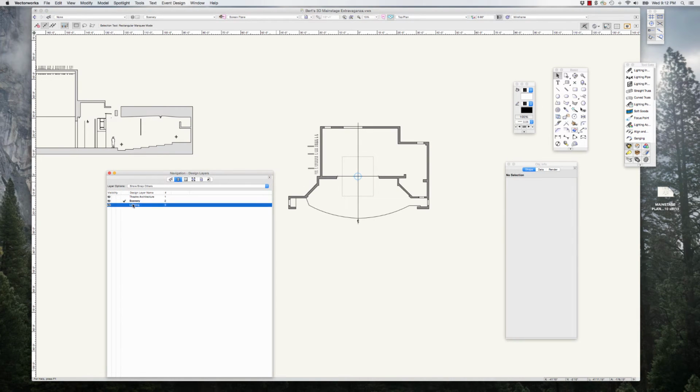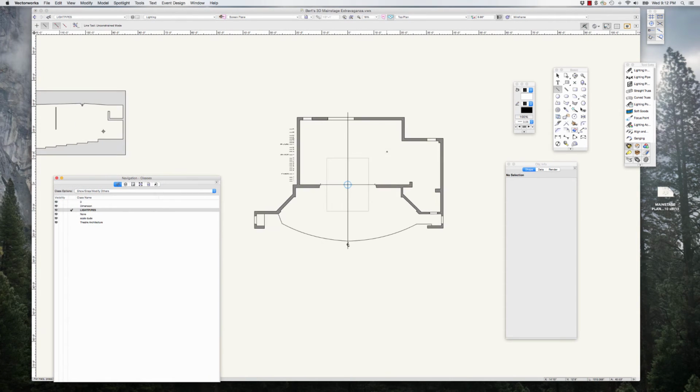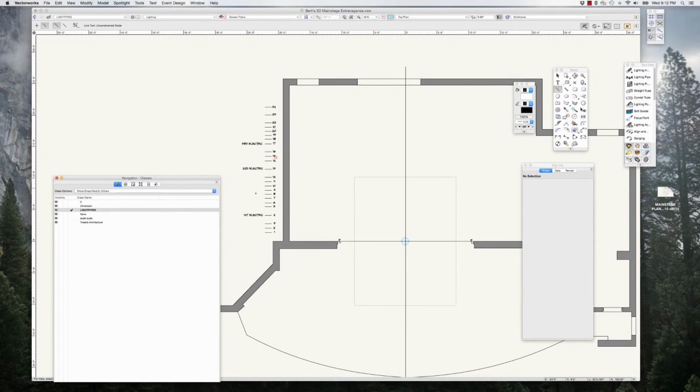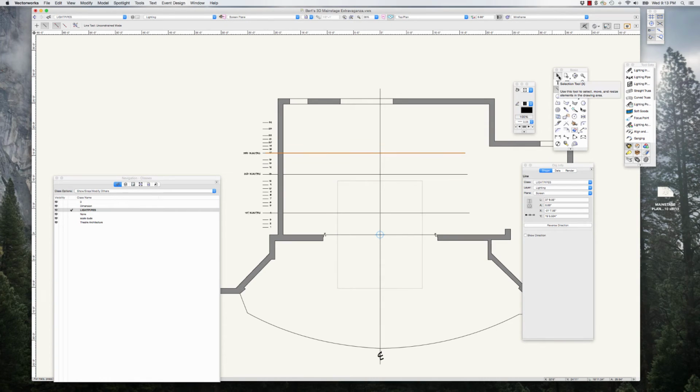So now what I want to do is draw in some lighting positions. So I want to go to the lighting layer. And I also want to go ahead and work in the light class, which we already have a class called light pipes, so we're going to want to work in that class, and then we're going to draw in the 3 electrics. So I'm going to do a little bit of construction lining here. I know where the 3 electrics are because they're marked here. So I'm going to draw just lines across here, so I can set these up. And then I know that our electrics, our pipes, are approximately 30 feet long.